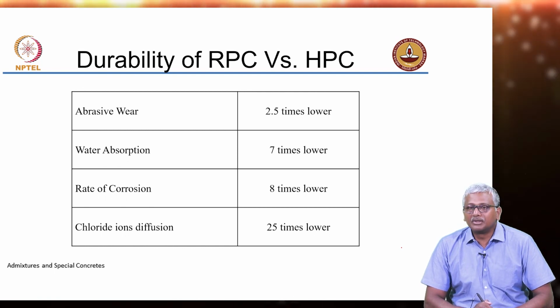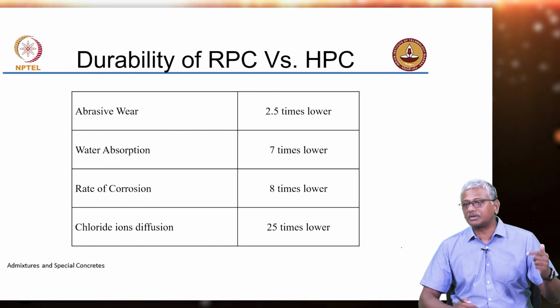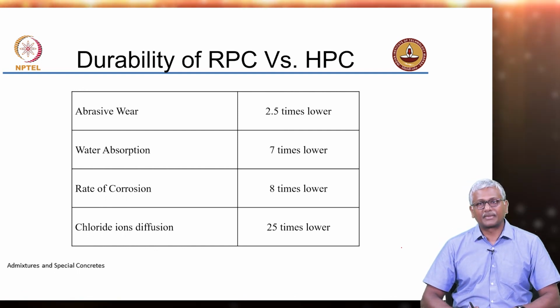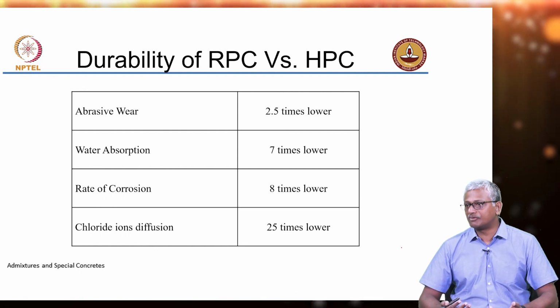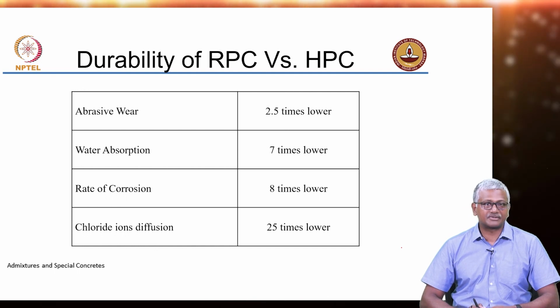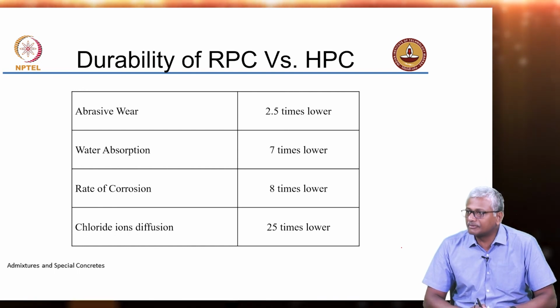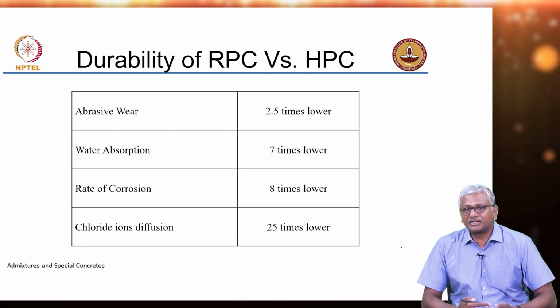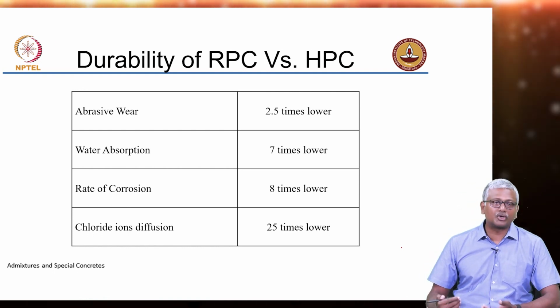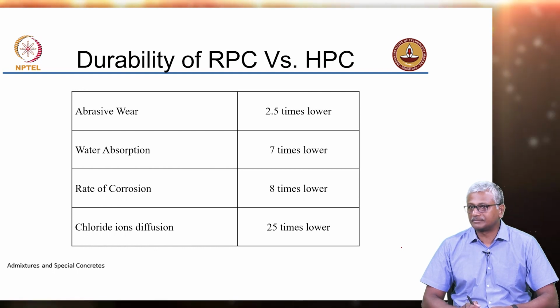It's not going to be a good result, because the fibers are going to conduct the charge, right. So you have to choose your test carefully to really show the effectiveness of the system. You can't choose an electrical test when you have fibers in your system, because it's going to show the effect of conductivity of the fiber, which is not really going to cause a poorer durability in your system.